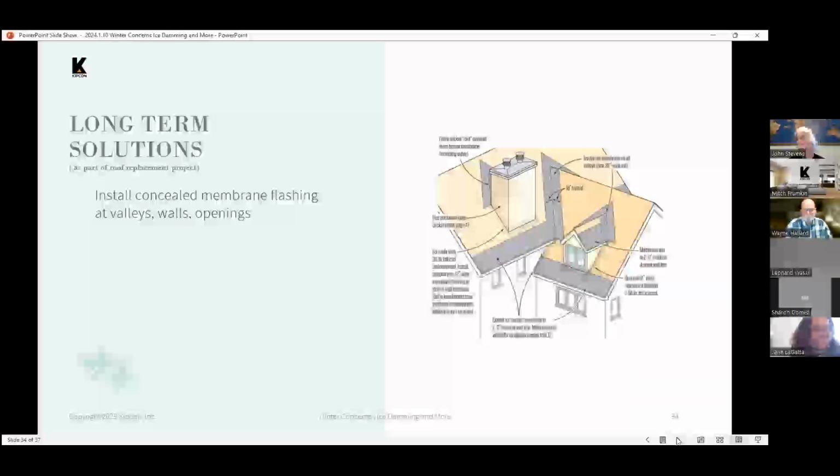Depending on the location of your building, the building code actually requires an ice barrier membrane to be installed at the lower part of the roof, at the eaves, where ice dams are the most common place that ice dams form.